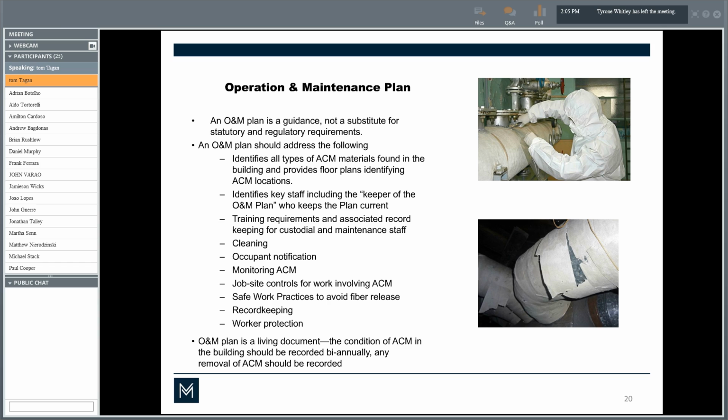And a thing that will make life easier for you as a facility manager over time is keeping that record, so that if you do a space and clean the asbestos out of there, like floor tile, you're then aware that that room has been done, or people who come after you are aware that that room has been taken care of and has been properly abated, so that work that gets done in there in the future is not going to need the same level of protection and precautions that you would do in a room that's never been touched.